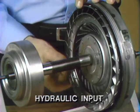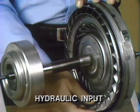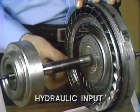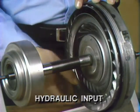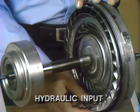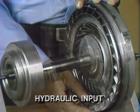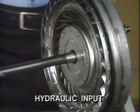Power is transmitted hydraulically from the impeller to the turbine, and then from the turbine to the sun gear, to the turbine shaft, and into the main gear train. This is 100% hydraulic input, and it happens in first gear and in reverse. In second and third gear, we have a split torque operation.